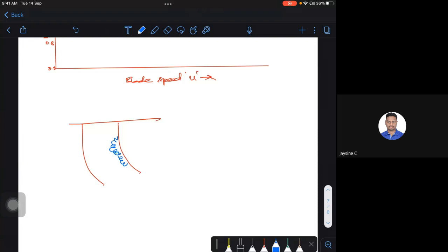A shock is formed because this is my velocity, the absolute fluid velocity. You might have heard of something called pre-whirling. Pre-whirling is nothing but giving a little bit of whirl to it, a little bit of induced whirl component. Otherwise, my Vw1 is equal to 0, and I don't have any whirl component.